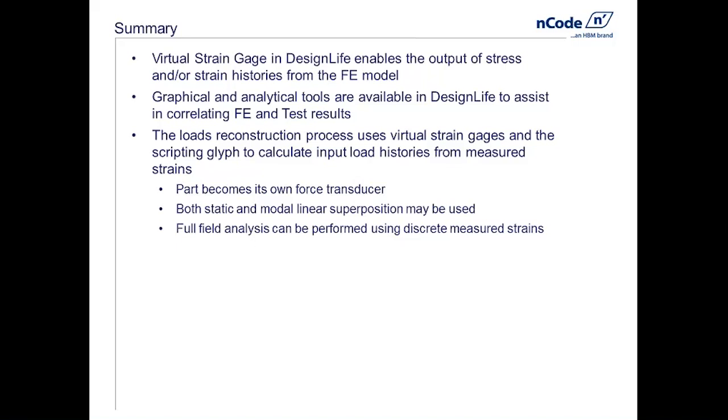Finally, we looked at the virtual strain gauge in conjunction with the load reconstruction process flow that allows me to take in a set of unit loads or modes, generate a response matrix of each of those loads to virtual strain gauges in the part, and then I can go in and pair up that information with actual measured data at those strain gauge locations, and I can recompute or reconstruct what would have had to been either the modal coordinates or the loads for each of my unit loads on my part.